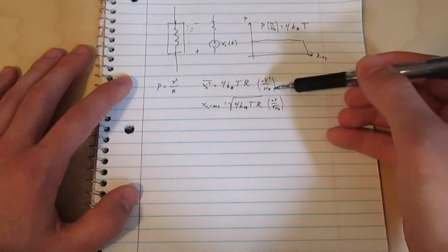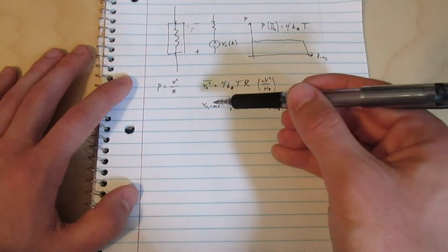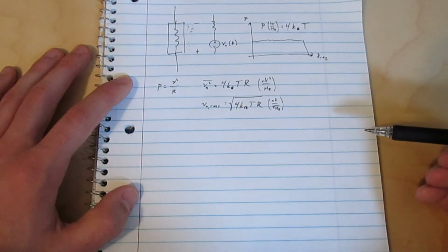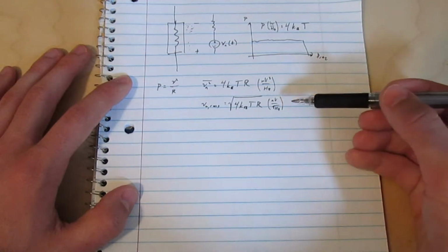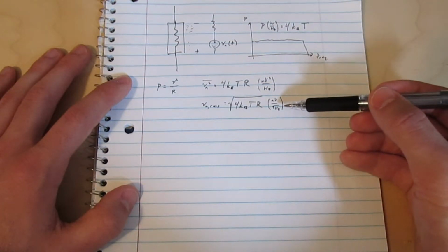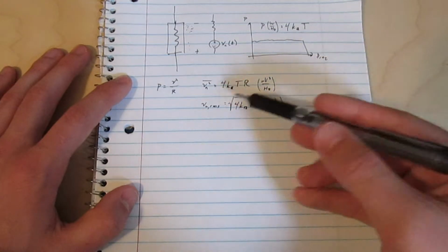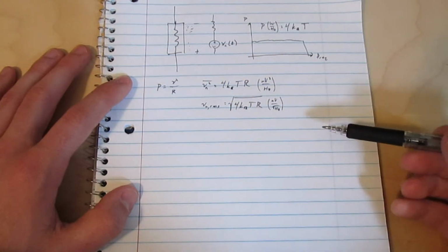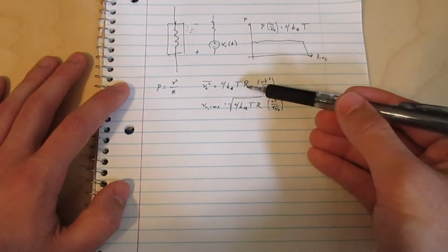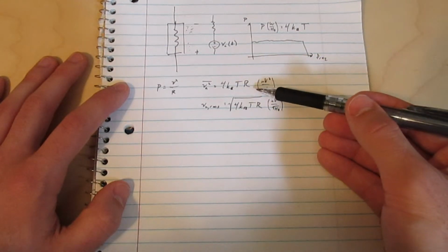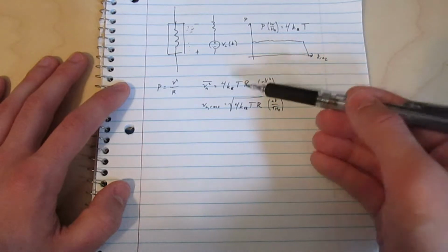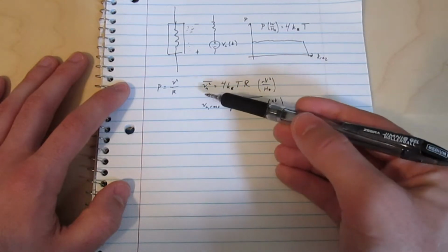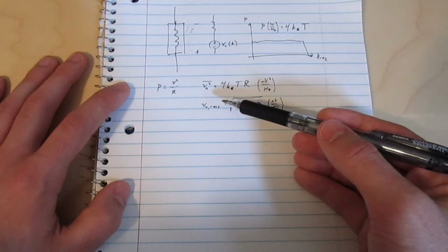And when you take the square root of that, you end up with the RMS or root mean square noise voltage. And the units for that are usually nanovolts per square root hertz. The square root hertz part doesn't really make all that much sense, but that's the number they usually put on the data sheets, so we got to deal with it. And from this you can see that large value resistors have more voltage noise on them. Small value resistors have more current noise on them, but since my circuit reads voltages, I don't really care about current noise all that much.